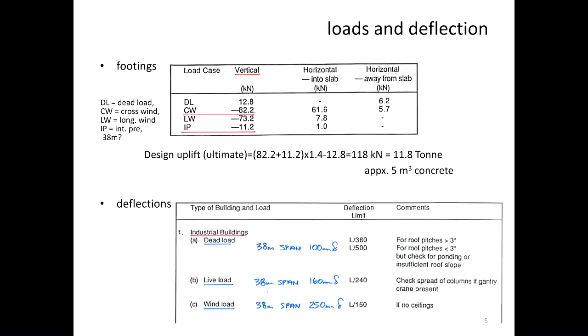So what we have to do, based on experience and a lot of design being done, the most critical load because of wind in this particular structure, because the height is closer to the ground, the worst case that could happen is the wind will just push it over from the foundation and sort of overturn it. So that becomes the design criteria in which we say it's the uplift case that we use to design what the integrity of the structure satisfies.